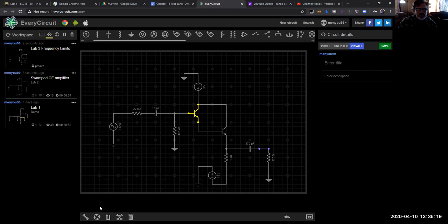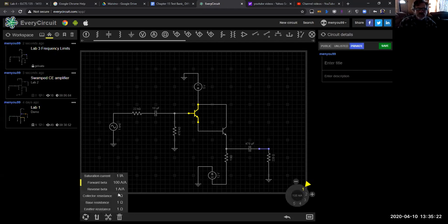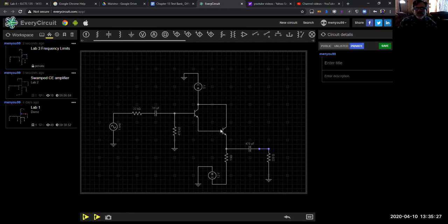Now, one of the things they call out in the directions is to assume the beta, but in this case, we can know we have it dead on, right? 100 beta on this and 100 beta on this, multiply that out, and what do we get? One with 4 zeros behind it, so 10,000, and I'm pretty sure that's what it calls out for. A lot of this is calculations, so we do have some good material in there for that. I posted up, with the recent lecture, what our prime is and that kind of thing. And then we get to actually notice what the Darlington pair does.